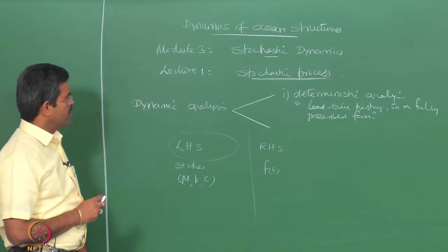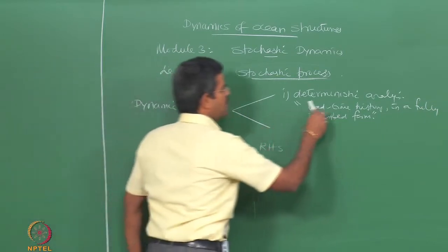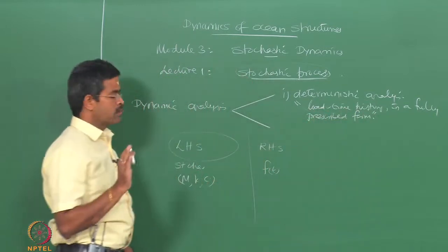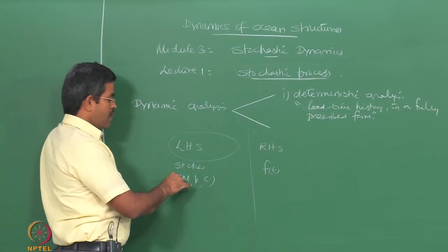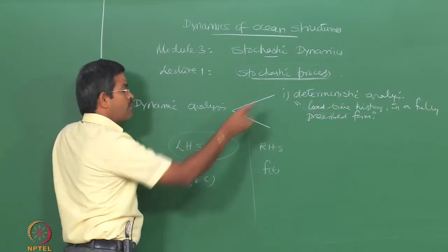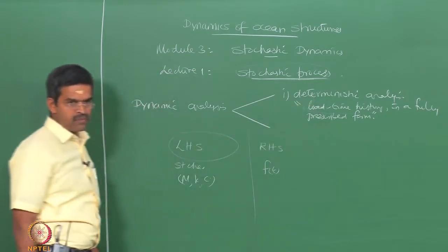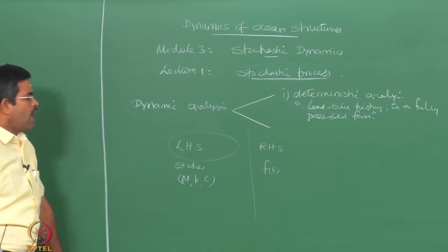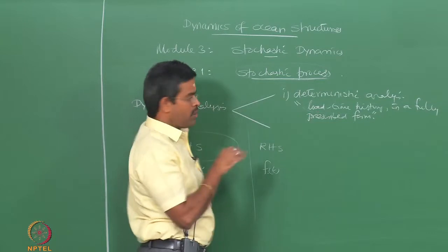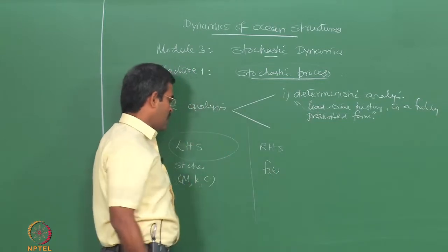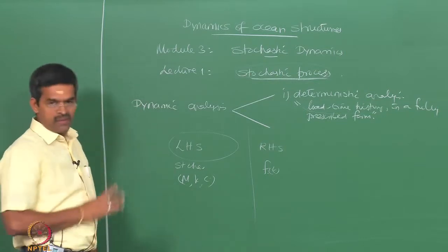So, on the other hand, when we talk about the load time history, we are not generally confused with the material characteristic, with the mass characteristics or with the damping situation in a given system, because generally they do not vary with time. However, loading will definitely vary with time, that is why we do dynamic analysis. If loading is also not varying, then the analysis becomes either static or, at worst, quasi static analysis. We do not do dynamic analysis at all.